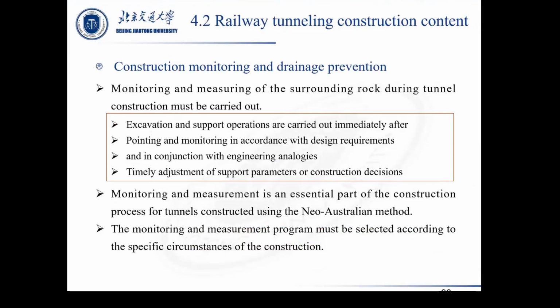And the monitoring and measurement of surrounding rock during tunnel construction must be carried out immediately after the excavation and support operation, with points and monitoring carried out according to design requirements and combined with engineering to adjust the support parameters or construction decisions in a timely manner.